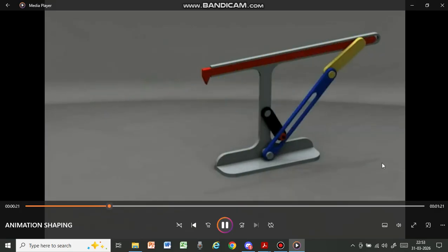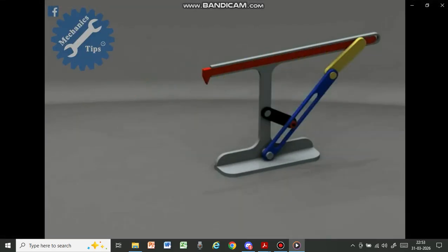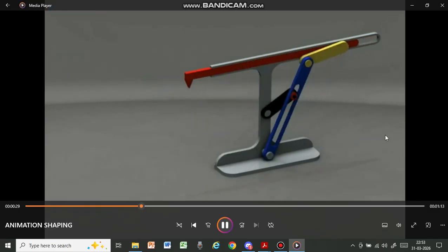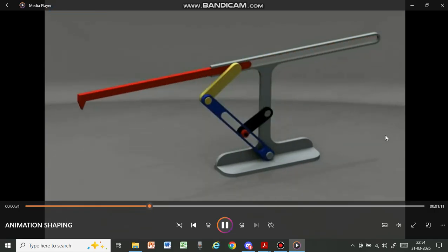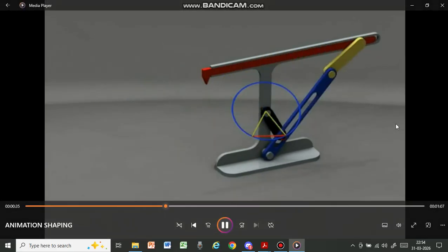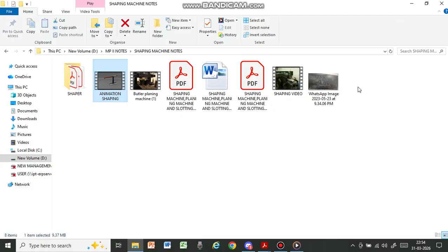In the considered configuration, the fixed pivot of the driven crank is located outside of the circle on which the driving crank moves. The angular speed of the driven crank is variable. The duration of the motion for its part corresponding to the small arc is shorter than the one related to the big arc. This is why this device is named quick return mechanism.